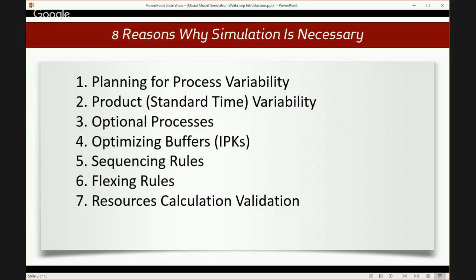How would our line react to this mix? Remember, we insist on this in class many times. We're designing a mixed model line on the basis of an assumption of mix and volume. That is your forecast daily volume. From there, do you think customers are going to order based on that? Of course not. They're going to give you whatever they give you. So you can take 2, 3, 5 bad days from the past and see what they do to the line with a simulation model. With that, you can tweak your resource calculations or validate them. Yep. And lastly, testing Kaizen projects.